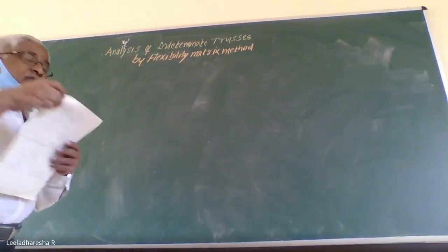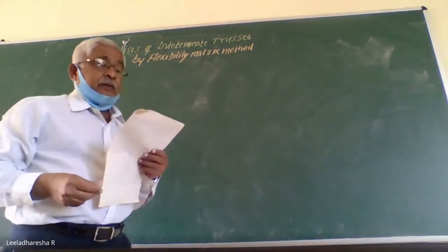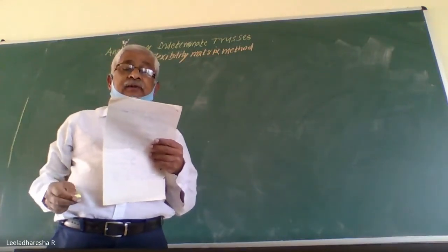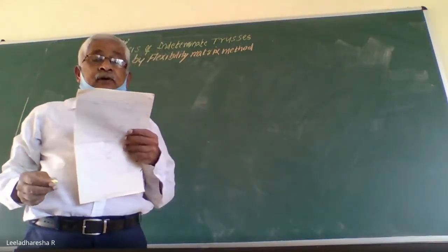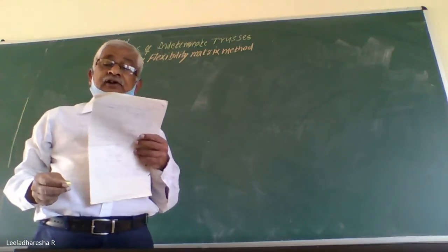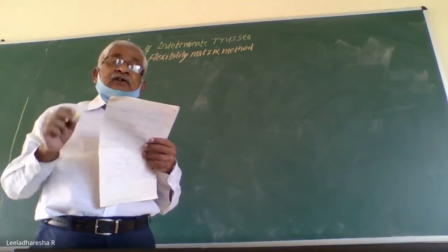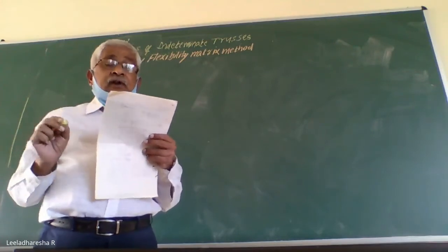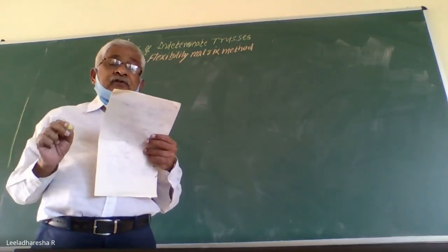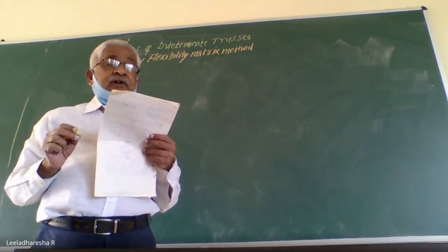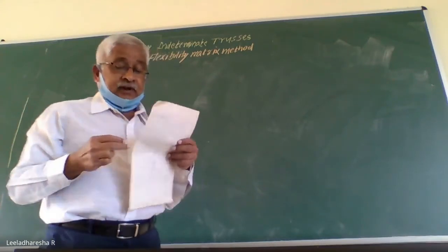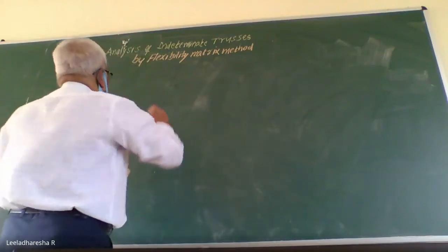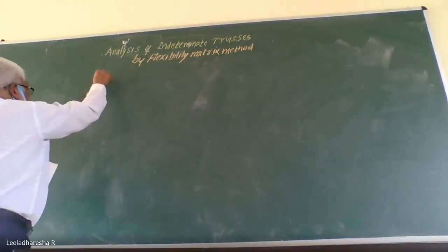The problem is: analyze the pin-jointed plane frame shown in the figure by the flexibility matrix method. Flexibility of each member, that is L by AE, is given to be 0.025 centimeter per ton. Everything is given in tons, so we will solve it in tons only.